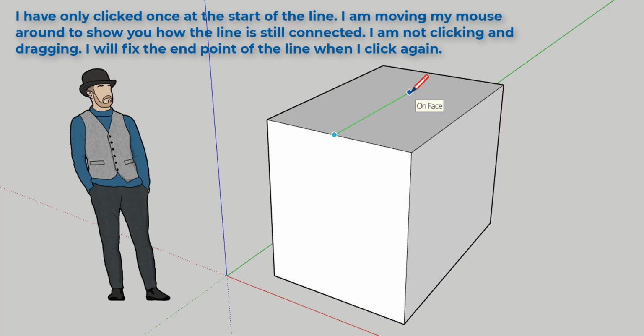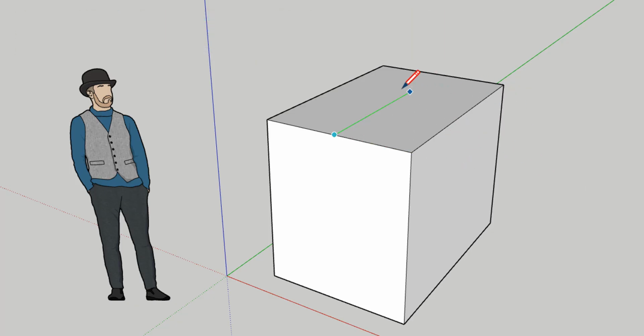Now, as I move it back, notice I'm getting a green line. That means I'm parallel with the green axis. Again, we're going to talk more about this later, but I'd like you to start intuiting some of these things. If I get off the green line, if I only have a black line, that tells me that I'm not in line with that axis. So you want to be. And actually, if you go back here and wait to get midpoint in the back, you will get that line looking green. By the way, if I go in the other direction on red, the line becomes red. If I go straight up, the line becomes blue. And we'll learn more about these axes later in the semester.